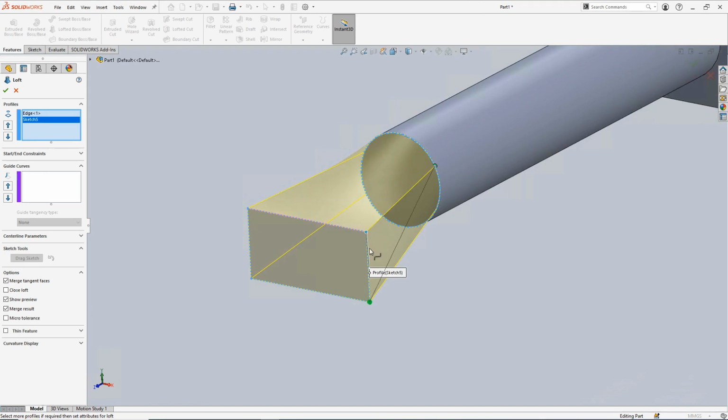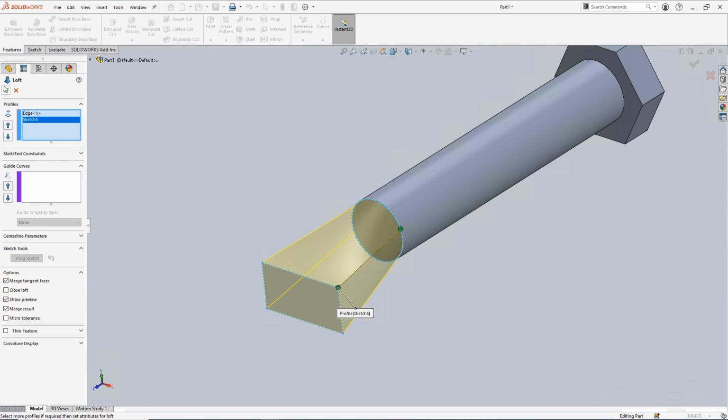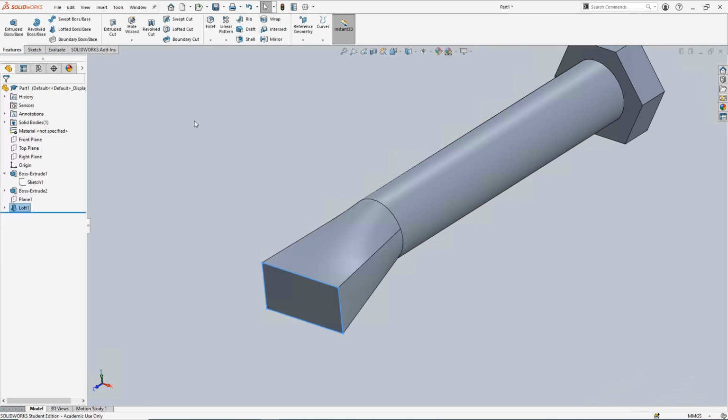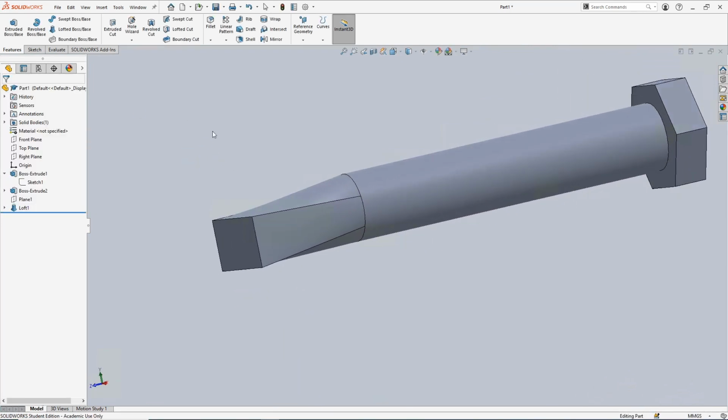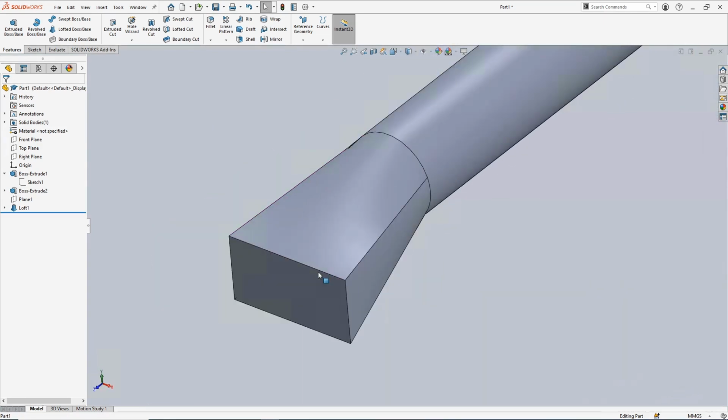So we can simply drag and drop these points, and that would produce different results. So you can make it more like twisted in this way, or you can rotate the control point on the circle if you would like to do so. But once you're happy with the control points, you can click OK. Then it would create a rather complex geometry using the loft feature.